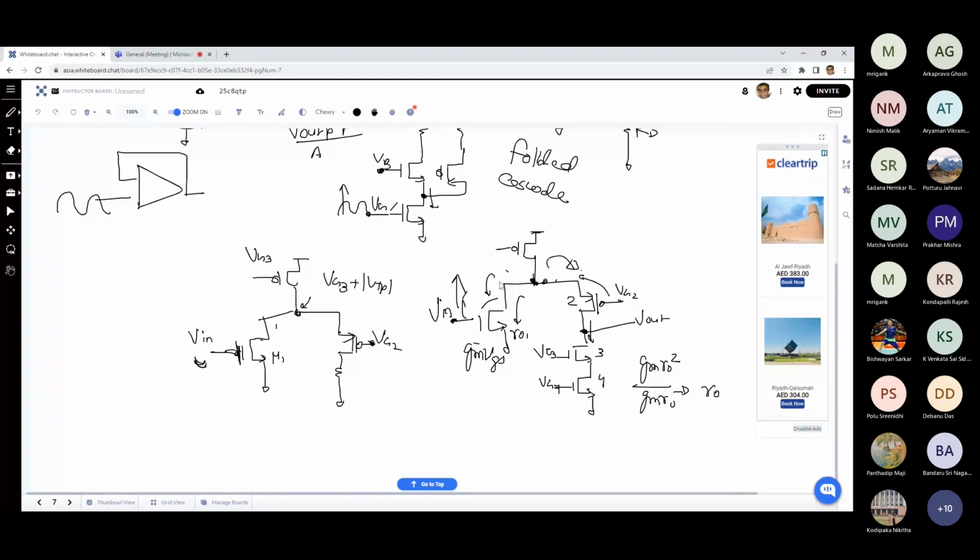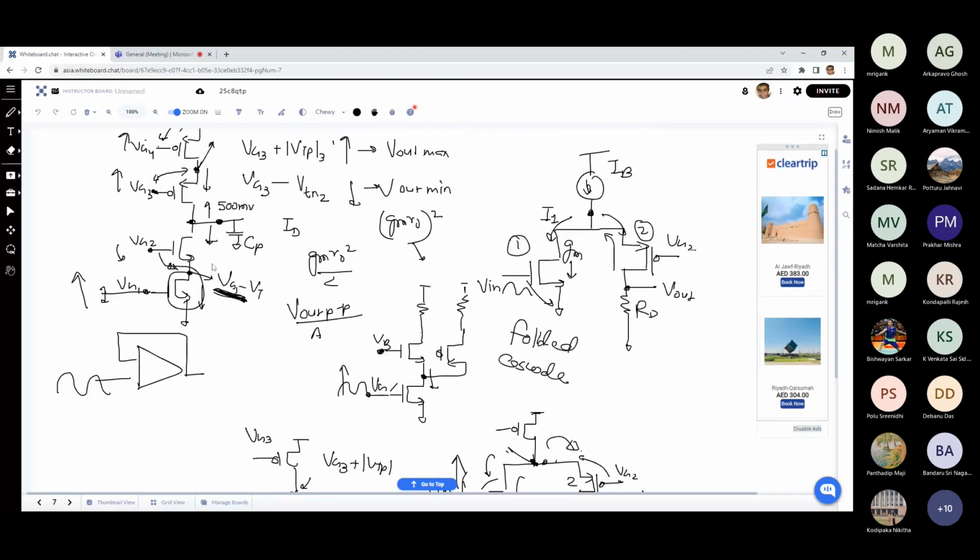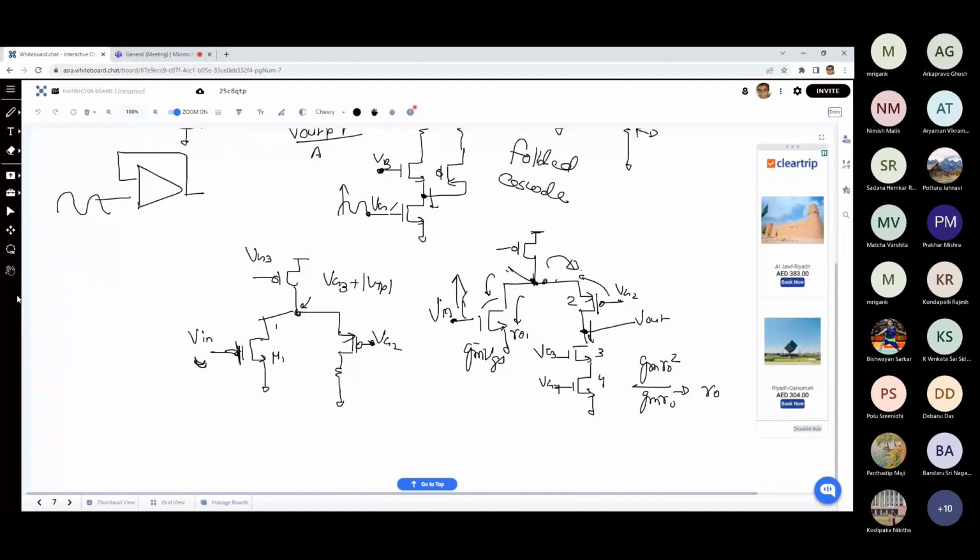So that will be useful for our folded Cascode operational amplifier. The main thing is we are decoupling the swing at the output to some extent from the input swing. So here the input level, we can ensure that it can go to a higher value based on the VG2 and the W by L of M2. This voltage you can increase. Earlier, the drain voltage of M1 was at a very low value to maximize the swing at the output. But in this case, that is not a scenario. So here, this kind of configuration can be useful, especially when we are doing voltage followers, etc.